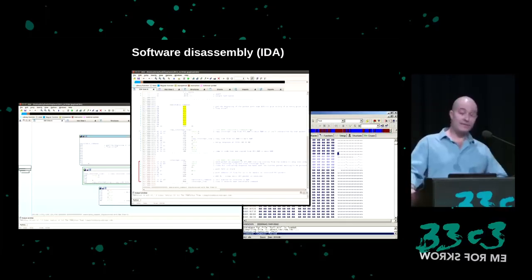Later, I remembered that I had looked at a previous version of the access controller from the same manufacturer, which was used in another system, VideoCipher 2+, an ancestor of DigiCipher. On the older chip was a copyright notice from WDC, who licenses the 6502 core IP. It was visible directly on the chip die under the microscope. So this would have been a great clue for the CPU architecture if I'd actually noticed it earlier.